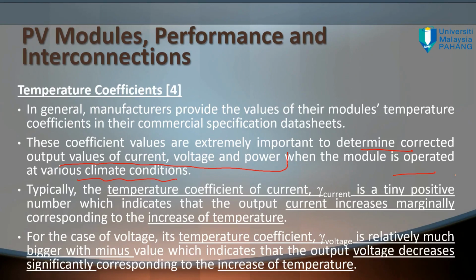That's the testing made based on those specs in lab condition. Lab condition is not the real operating condition. It's not exposed to the real sunlight that you feel when you go to class. That's different. It's tested under lab condition with a controlled temperature, because the cell temperature must be kept at 25 degrees C. That's why everything is controlled. So the STC is the control environment. It's different from the real operating conditions.